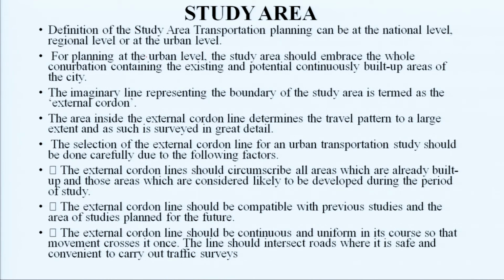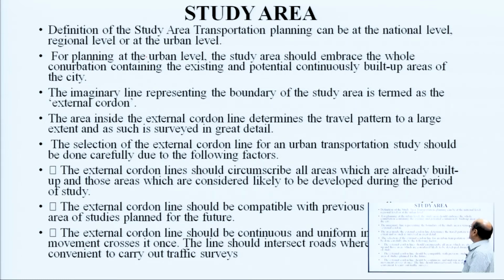Now, come to the next one, study area. Definition of a study area. Transport planning can be at the national level, regional level or the urban level. For planning at the urban level, the study area should embrace the full conurbation containing the existing and the potential continuously built up area of the city.